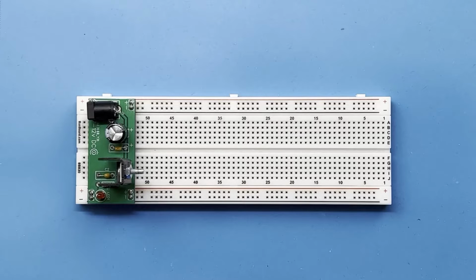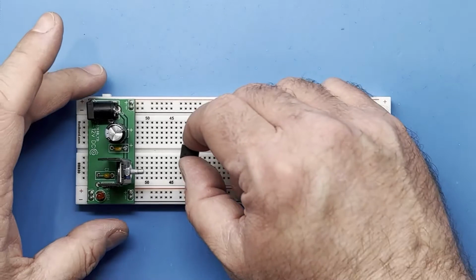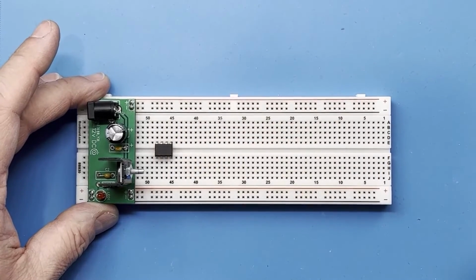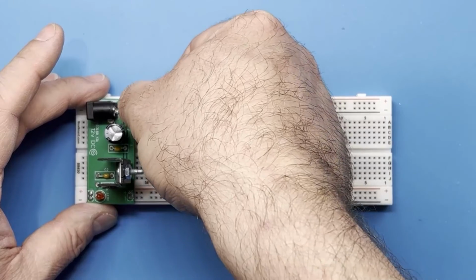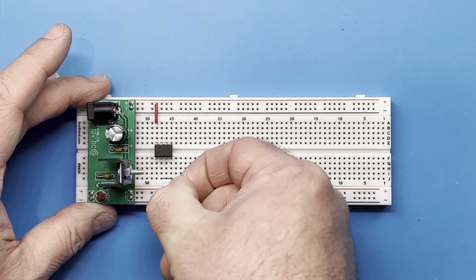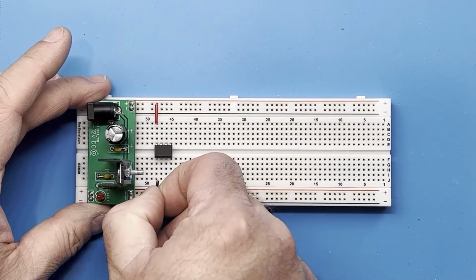I didn't show this in the last video because I'm only going to be using it while we're initially testing our circuits. Once you get into running programs from ROM, where commands can take 20 or more T cycles, pushing the button gets old very quickly. I'll put the 555 in here, and then I'll hook up power, and then ground. And keep in mind that ground on a 555 is pin 1, not pin 4 like it is on logic circuits.